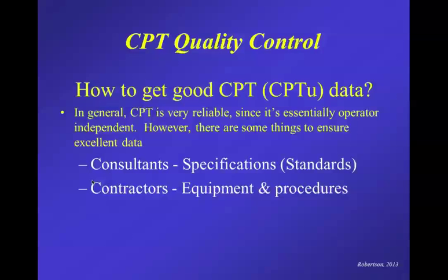So the CPT is far better than the traditional methods of drilling and standard penetration tests, but there are some elements that it's useful to keep in mind about how to ensure that the data is as high a quality as possible, given the ground conditions, etc. So for consultants, as I said, that's often focused on the specifications, and for contractors, the equipment and procedures.